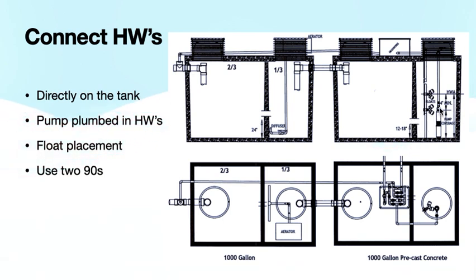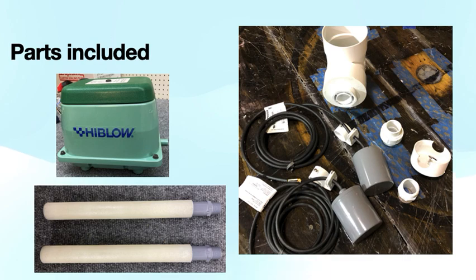And again, this pump line coming out, we just want straight pipe, unless specifically noted in your design or engineering, no check valves needed, just straight pipe elbowing over with a union there, and then elbowing again. So just 2 elbows, everything's pressurized, so just elbows, make it nice and neat, and that's what we're looking for there with the internals of this second pump tank going into the headworks directly on top of that second tank.